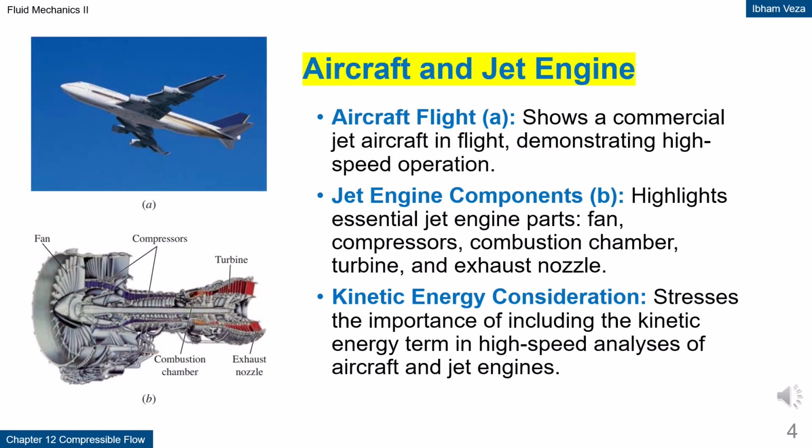Aircraft and jet engine. Real applications of compressible flow are shown through aircraft and jet engines. At high-speed conditions, kinetic energy cannot be neglected in the energy balance. Each jet engine component operates in a compressible flow regime. Significant pressure and temperature changes occur along the engine. This explains why compressible flow analysis is crucial in aerospace engineering.